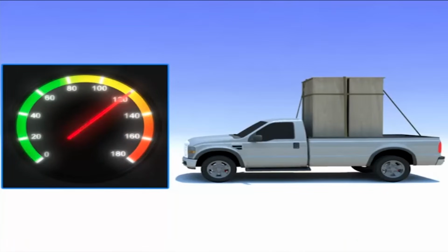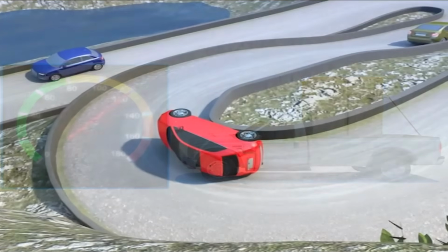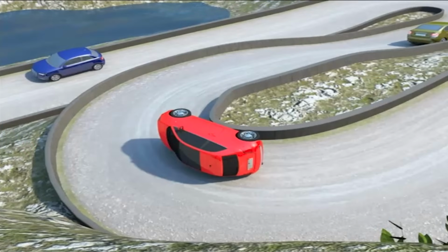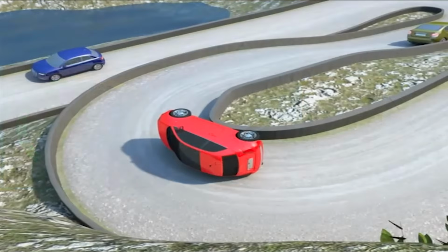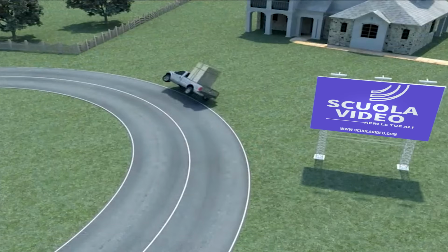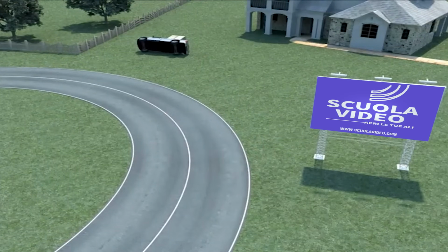In that case, we must be very careful in the quizzes. So far, we have talked about slippage due to low grip and grip coefficient. Now let's talk about overturning when cornering. Vehicle overturning when cornering is favored by a high or unstable load and by high speed. In addition, the overturning force when cornering is favored by a small radius of curvature of the road.